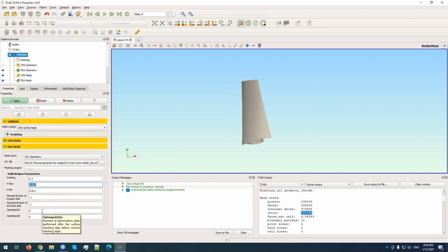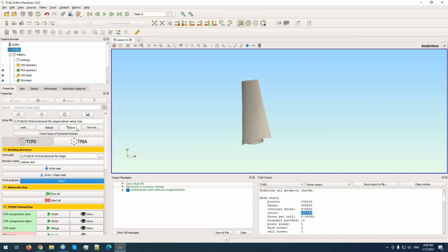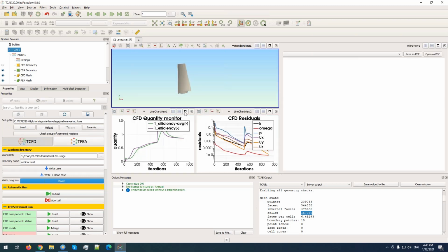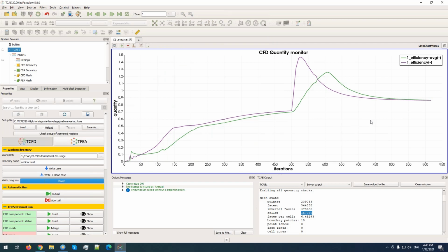All the other parameters are parameters of the solver, the NetGen solver. So basically we care just about these two parameters and the input STLs. So I will click apply, I will save the data, and now we should wait for the results.